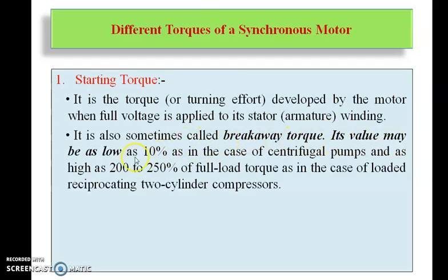Its value may be as low as 10% as in the case of centrifugal pumps and as high as 200 to 250% of full load torque as in the case of loaded reciprocating two-cylinder compressors. That means starting torque is the torque which is used to start the motor.